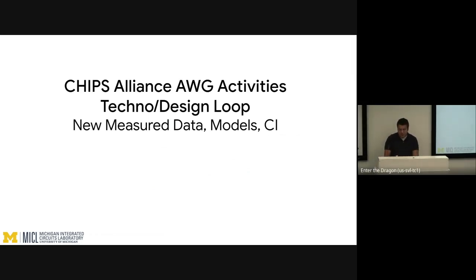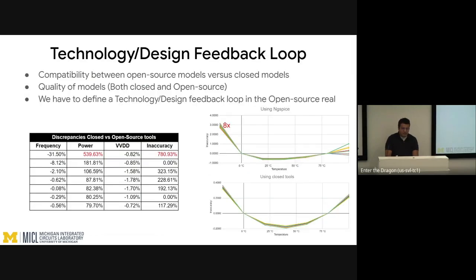So that was a really cool thing to see the past months here in our analog working group. But one thing, before jumping there, I want to give you an example of issues we can see, right? We can get silicon working, and we can design things, but NGSpice, when I simulated the temp sensor I showed you earlier in Skywater 130, was telling me, hey, you have a 3°C inaccuracy at -40 or -20.